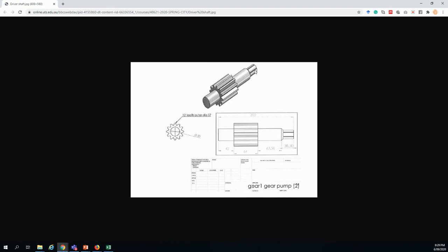To cut the gears on the milling machine, we need to use the indexing device, which can divide the circle into equal parts, not equal angles, equal parts. Usually, the shape of the teeth and the dimensions or the pitch diameter are all going to be a standard item. So you can find about this by doing a simple research.